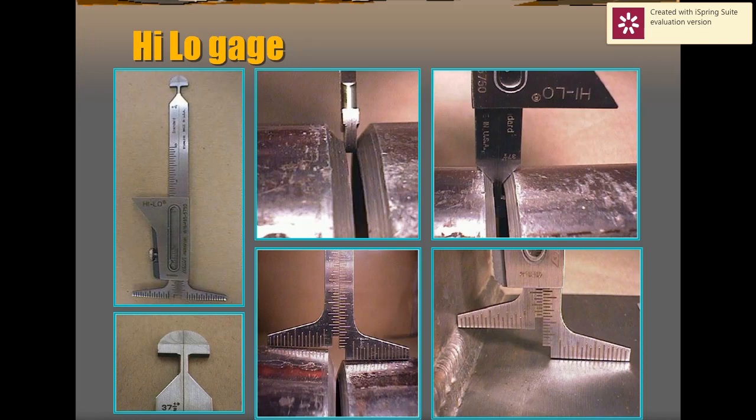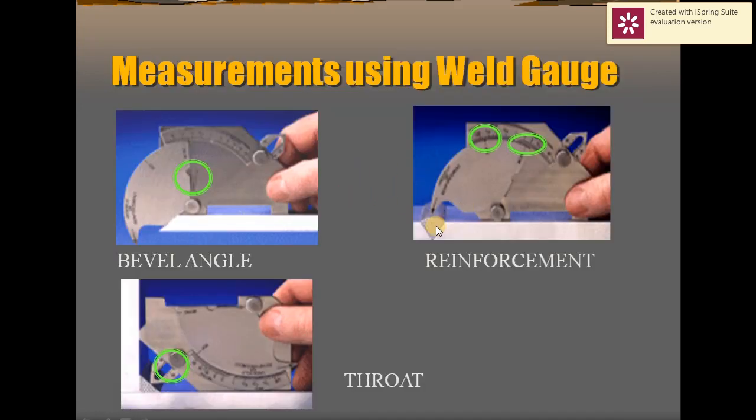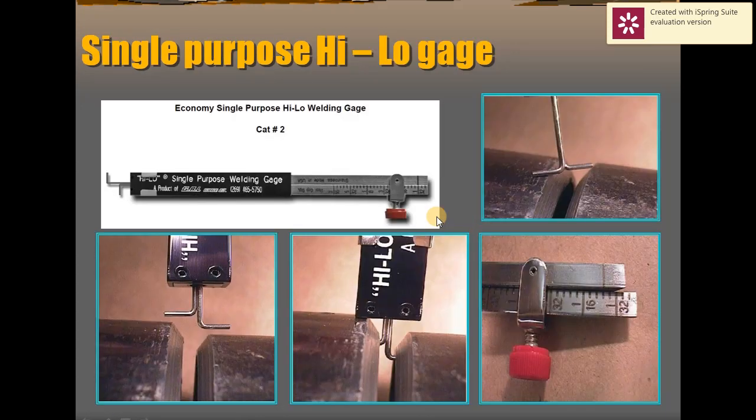The Hi-Lo gauge is mainly used to find the mismatch between the welded components. Before conducting the welding, with the support of the Hi-Lo gauge, you have to measure the surface area and ensure the edge preparations are equal. Only after that should you conduct the experiments. Otherwise, variations will occur. As already said, the reinforcement will vary.